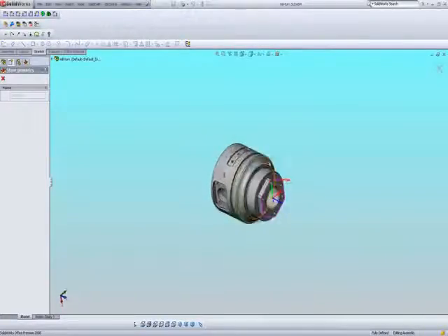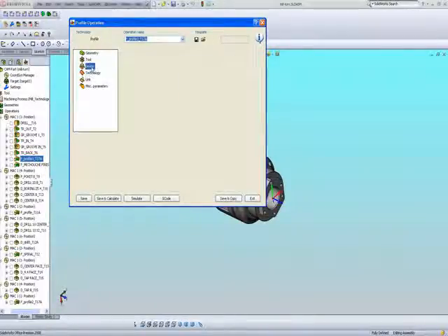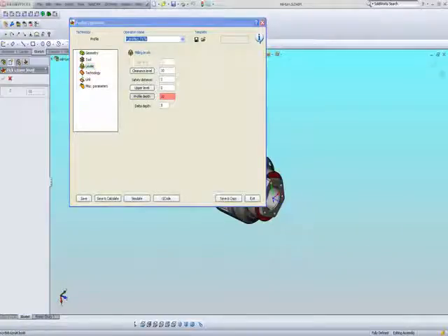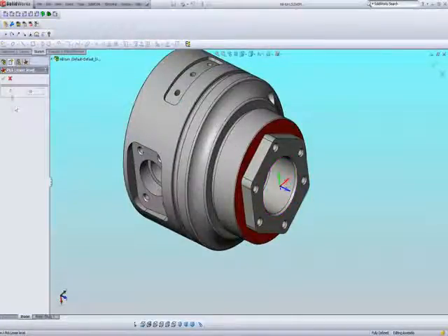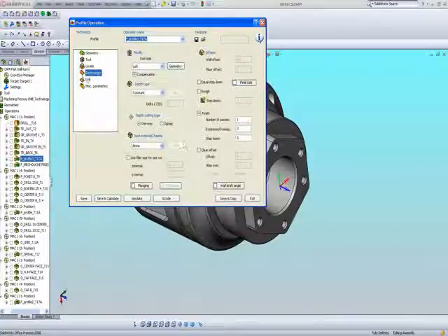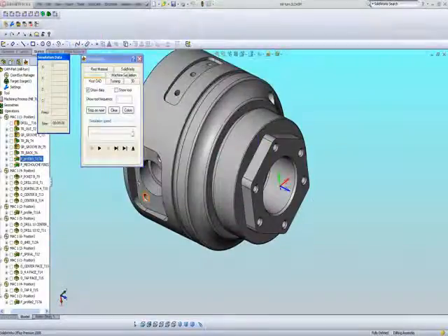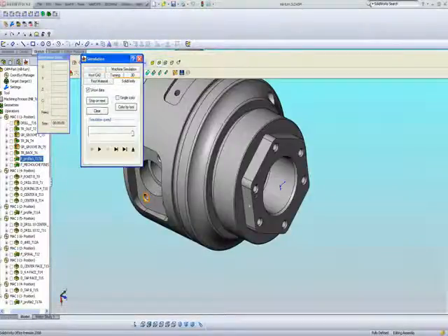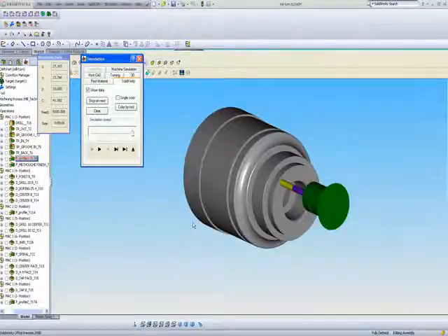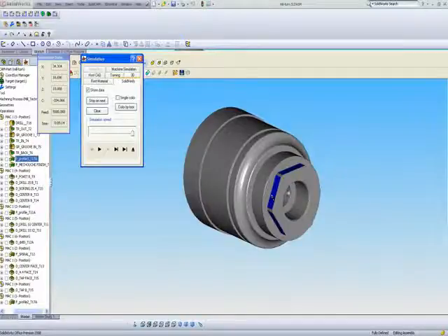my geometry, my technology, my upper levels, my profile depth, as shown here, my regular milling technology, my links, approach as a tangent, lead out also as a tangent, and if I were to do my simulation using your Solid Verify, you'll see that my tool simply will go around this area and would simply mill out the entire area as seen over here.